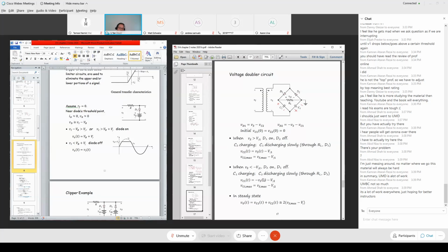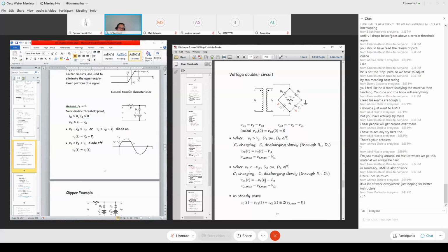And during the negative cycle, when Vs gets to its negative maximum, then minus Vs becomes positive, Vs maximum. Because Vs itself is negative, that negative maximum multiplied by the additional minus sign turns into the Vs maximum. So capacitor 1 also charges to this amount.